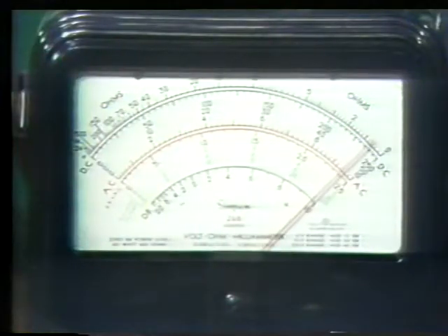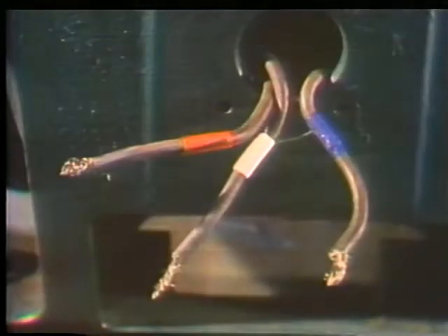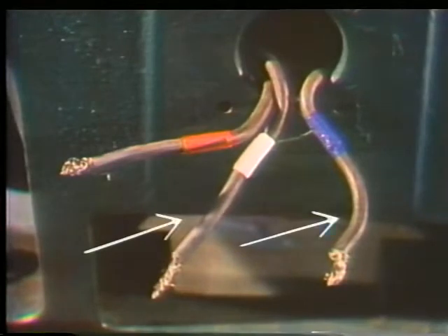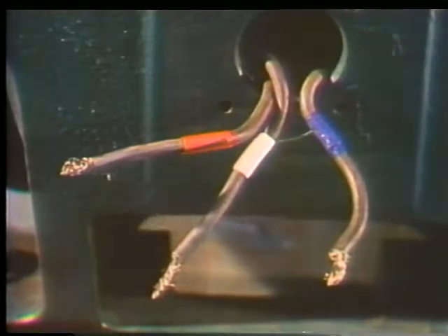The multimeter reads normal resistance. Now we know for sure that the open can't be in coil 2 or coil 3. If there were an open in either one of the coils, this current path would not have normal resistance. Since it did, we know the open is in coil 1. Don't ever assume that you know exactly where an open is until you check every one of the current paths.